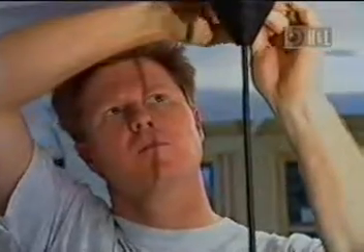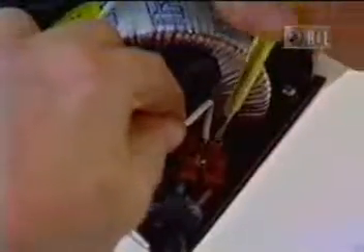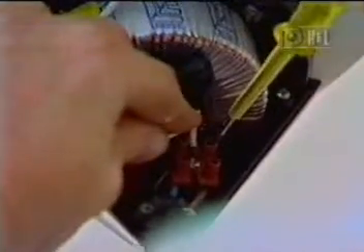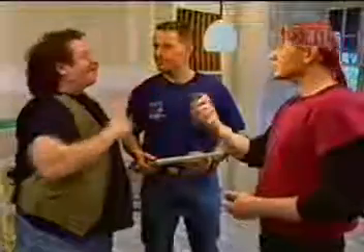Remember, all fixtures come with directions. Follow them, please. For this fixture, pull the Romex cable through the mounting plate and attach it to the ceiling with the screws provided. Snap the fixtures onto the plate and attach it with the screws provided. Now attach the wires to the terminal blocks as indicated in the directions. Where are the directions? Pendant's up and it's lit.